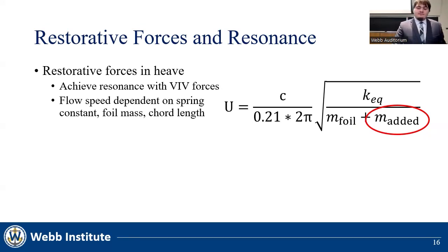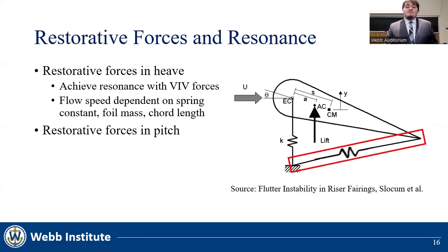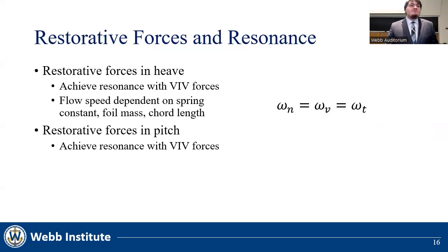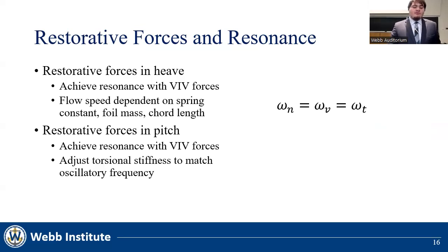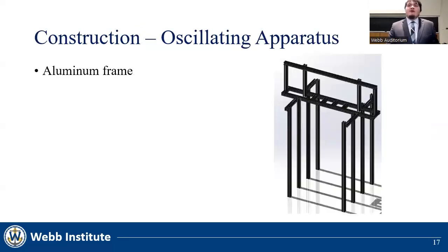foil moving through water. We also added restorative forces in pitch, again to achieve resonance between the pitch natural frequency of the foil, the heave natural frequency, and the frequency of VIV. The whole point of this was to adjust the torsional stiffness to match the heave natural frequency as closely as possible. So I mentioned we built a new apparatus for this.